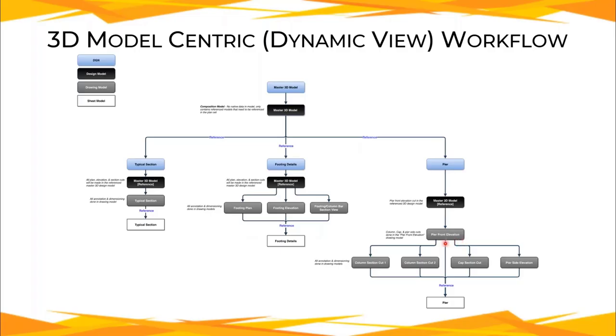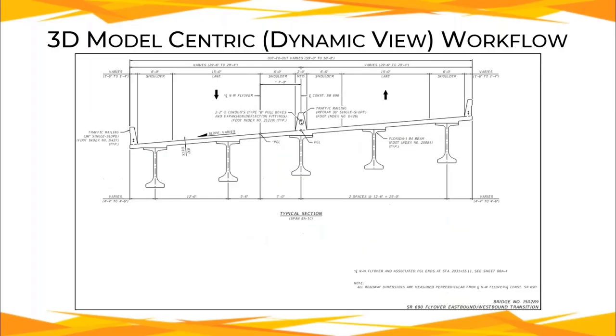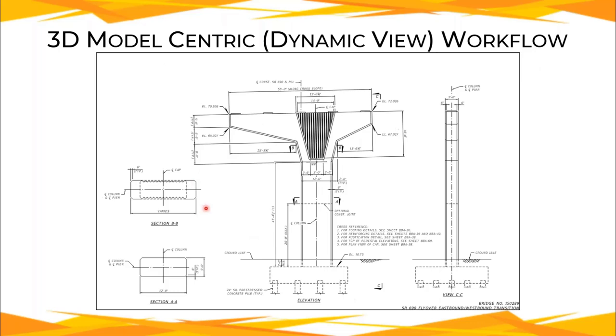And then when I do that, it's going to create these separate drawing models here, which I can go and annotate and add dimensions, whatever I need, relative to those specific views. And then in the end of the process, I'm going to reference all 5 of these models, all of these gray drawing models you see here, one by one into that sheet model and then move them around as needed and place them where I want on the sheet to produce this particular plan sheet here.